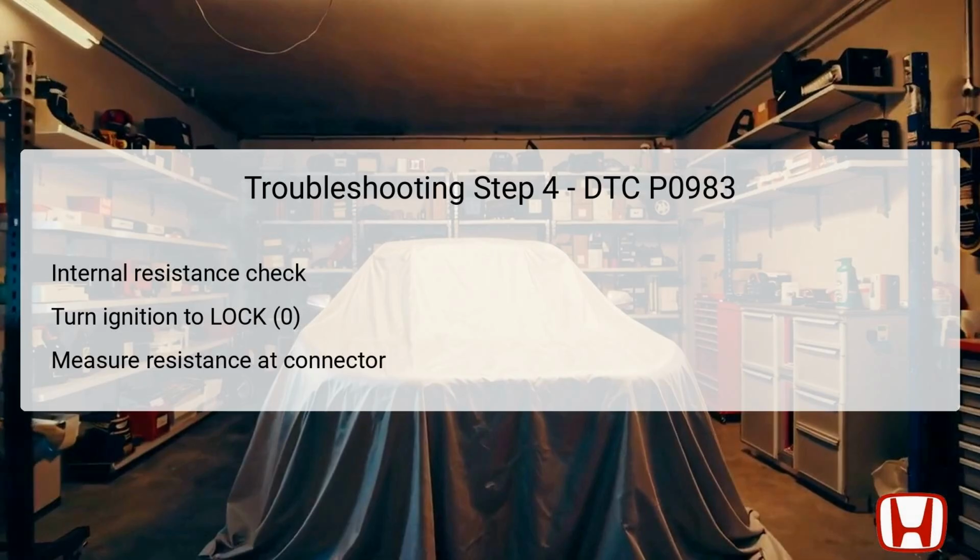Following the defined test circuit, measure the resistance between test points. This involves connecting one probe to the PCM connector C number 32 and the other to a ground. The resistance should ideally be measured between 13.8 to 17.1 ohms. This range confirms that the solenoid is functioning correctly.